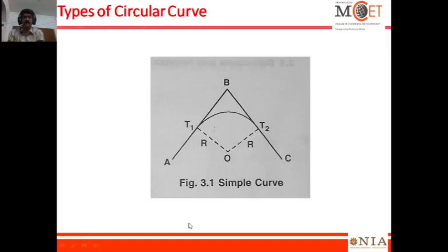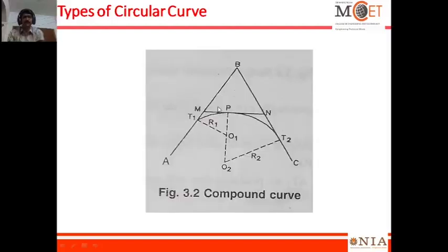Okay. So this is the simple curve for the two approach roads or tracks. We need to make a small curve such that the radius of the curve is with the origin O, and the straights become the tangent for it. And if the two straights' gap is too far and the meeting point is also too long, I need to make it simple and smoother.